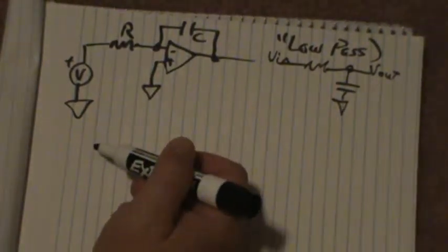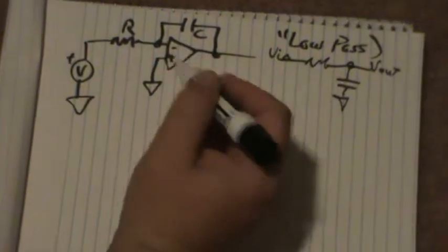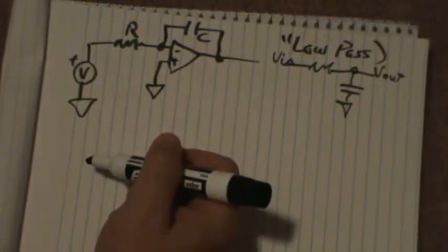Again, the op amp has really high impedance and all kinds of nice properties like that, which this one does not have. You put a load on here, you can drag this down. You're not dragging this down. So, nice properties here. We're going to stick with this one. This is first order, so in that sense, the low pass works out good there. I guess I should actually use quotes there.